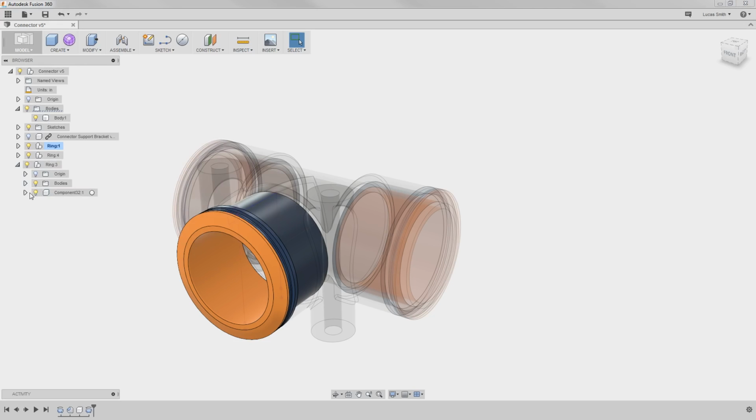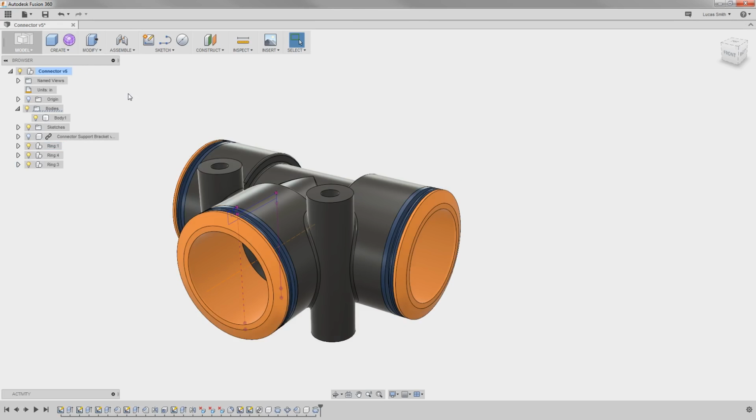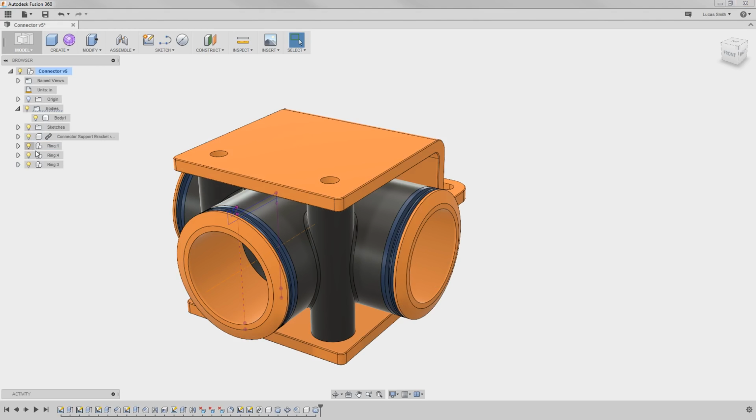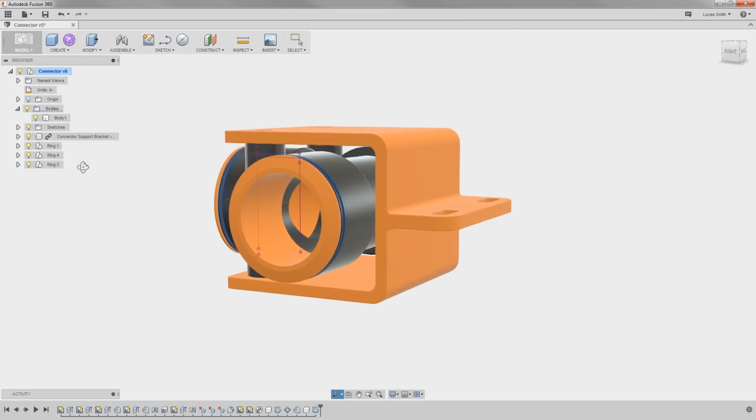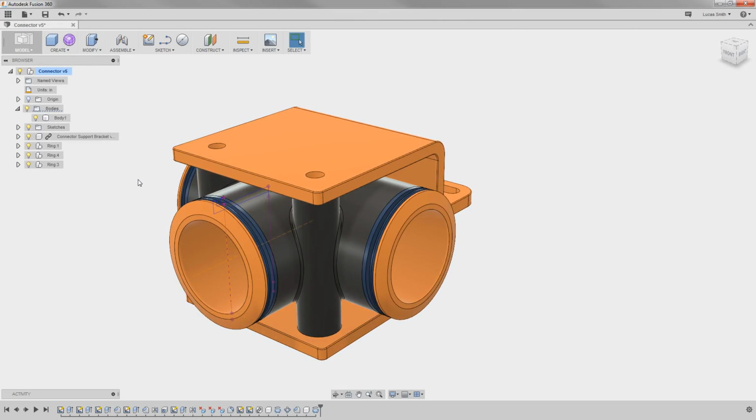So this method of activating either a component in the design or the top level of the design is how you can control the assembly structure. You can easily make decisions about the items in your designs that you would like to behave like components and simply repeat it as additional instances, or if you would like to add bodies that behave like other parametric features in the timeline, which can become components down the road at any time.